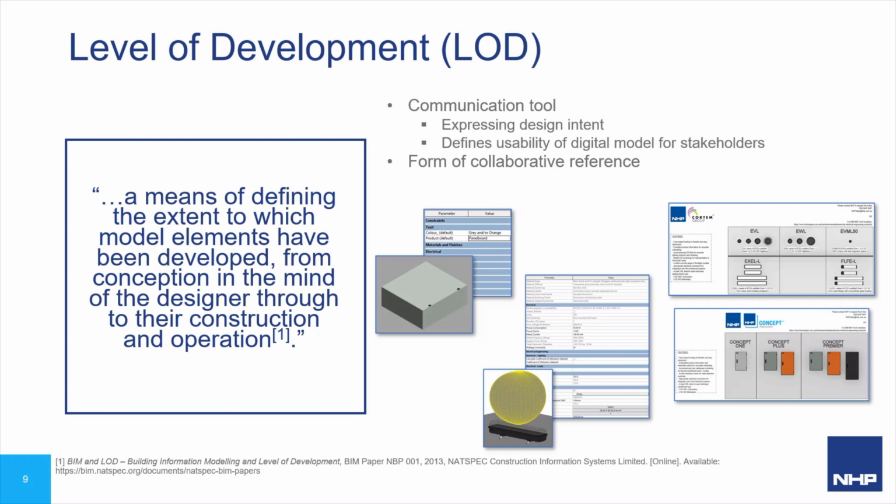The level of development selected depends on the intent of the Revit project being created. If you are creating a Revit project to simply communicate the location of certain products inside a building, LOD 200 to 300 BIM objects may be sufficient. Which leads me back to my previous comment about importing 3D files.